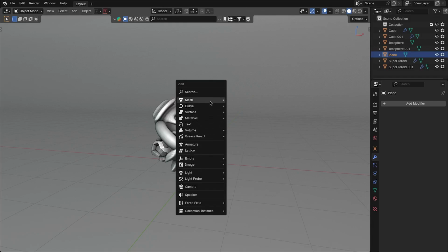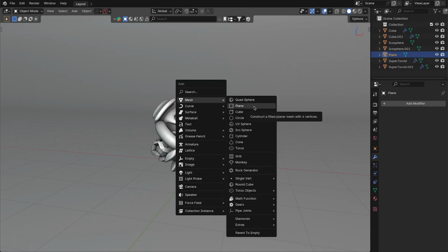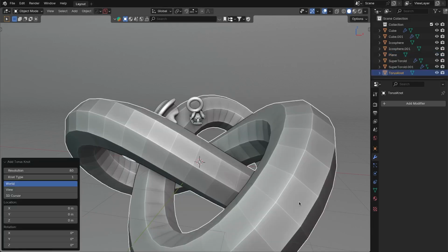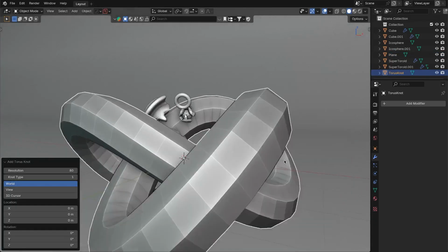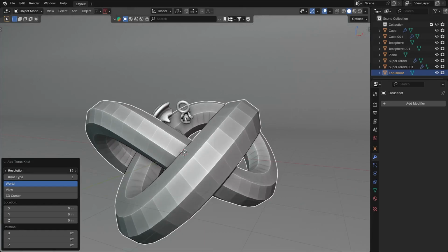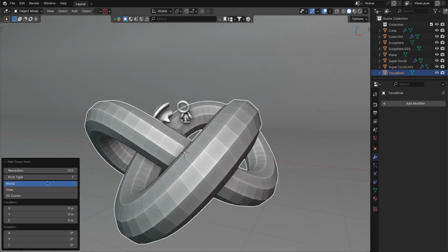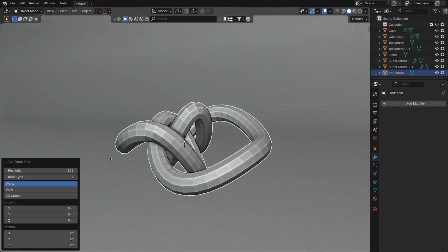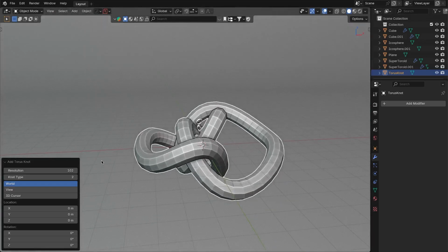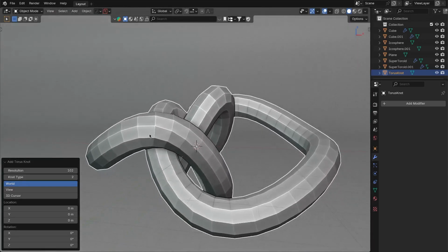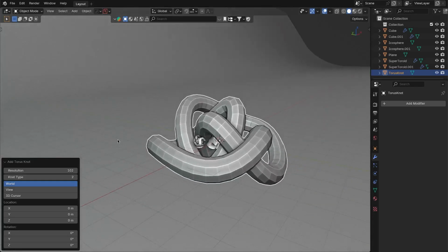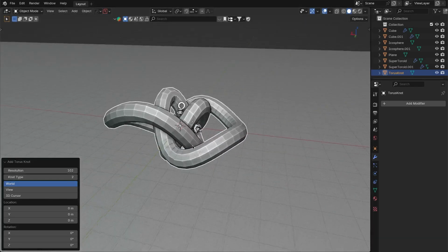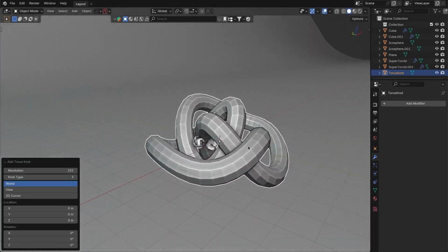All right, so now I think I want a shape for the background, so I'll do the torus. This is another free add-on with Blender. It's extra mesh options, so I have that on and installed, and it gives me these different options of torus that work really well for creating movement. They're just very complex shapes already off the bat.